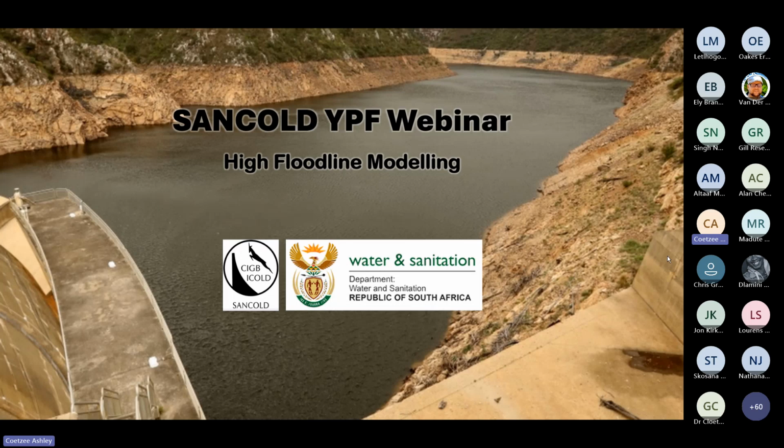Brandon, do you remember? Yeah, I was just trying to check now. Sorry, I did the study back in 2022, so I don't remember what the exact depth was, but it will just be subtracting the water surface elevation from your high flood line from your full supply level to get that flow depth over your spillway. Yeah, I hope that answers this question.